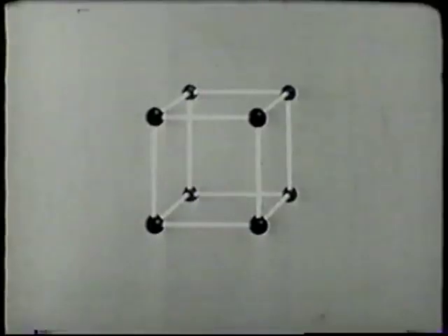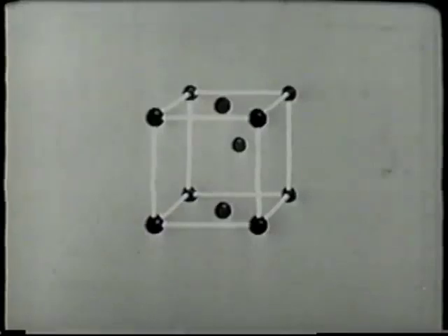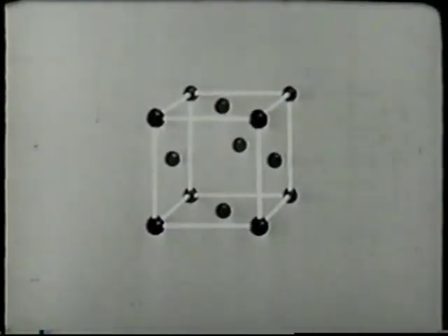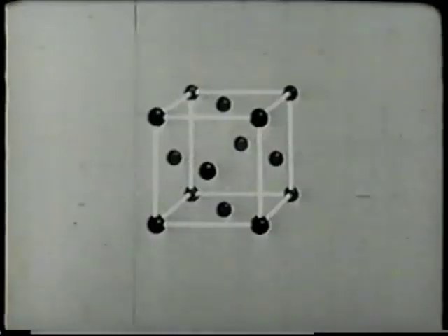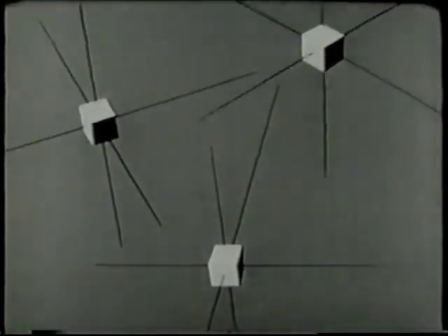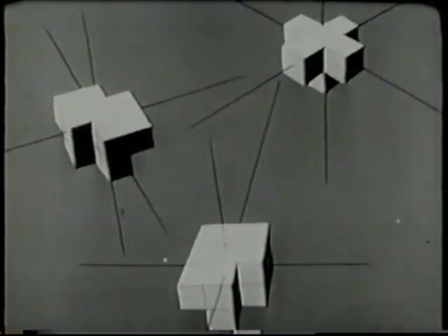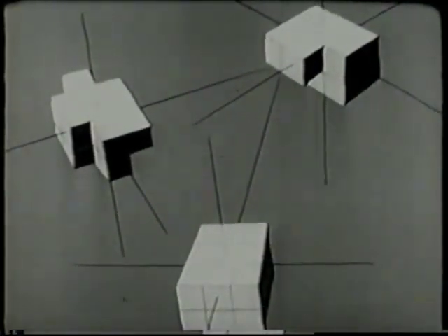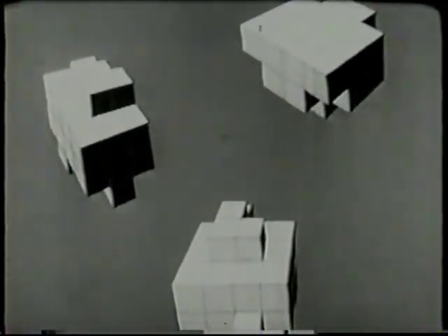The single lattice or unit cell is conceived to be cube-shaped, with atoms of the metal arranged in regular order, one at each corner and one in the center of each face of the cube. Aluminum unit cells are classified as the face-centered cubic type. The axes of these unit cells are oriented or aimed at random in many different directions. Each crystal formation expands and becomes a larger unit known as the grain.